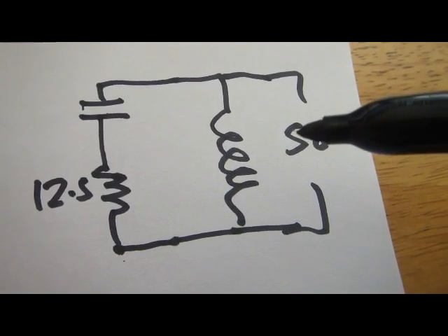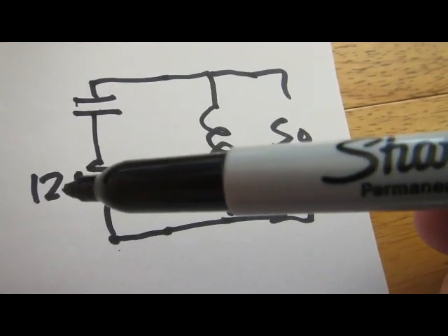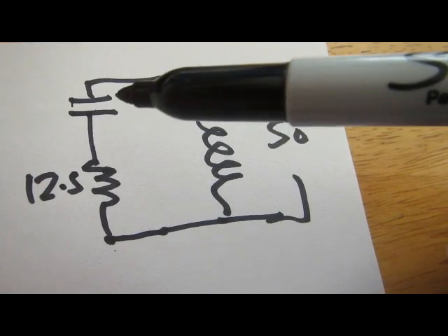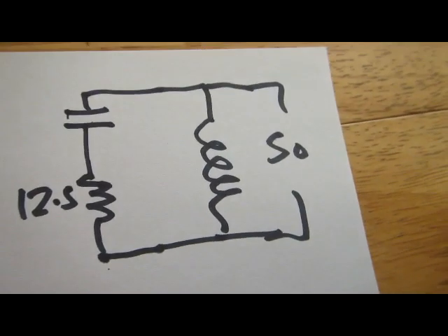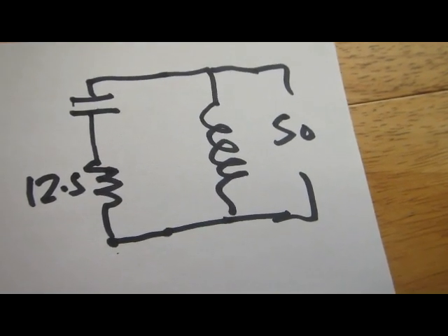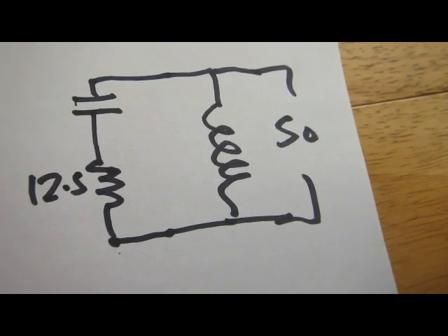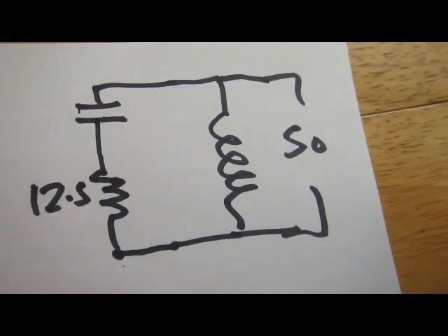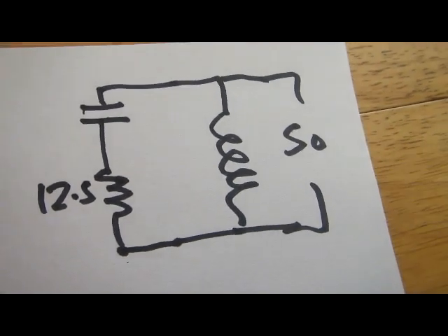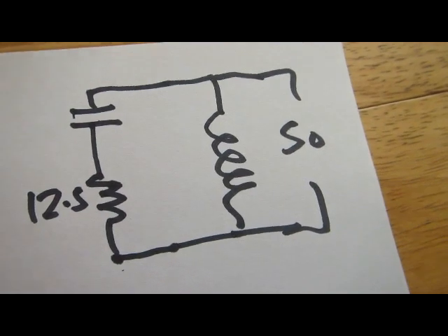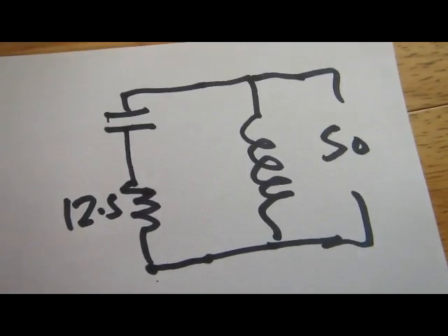Yeah, so that's the way around it goes. If you were using, suppose this was 40 ohms, when I calculated the reactance to use, I would have to use that exact formula for Q. Do you remember I said Q squared? We would have to use Q squared plus 1, but this doesn't very often happen. The maximum error you'll get is 2 to 1 error if you ignore that. So very often you'll get a mental arithmetic answer that's pretty close.